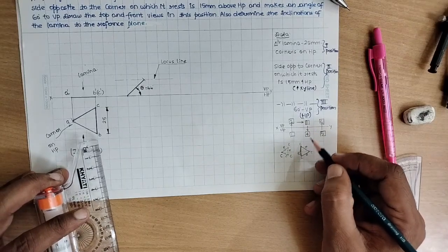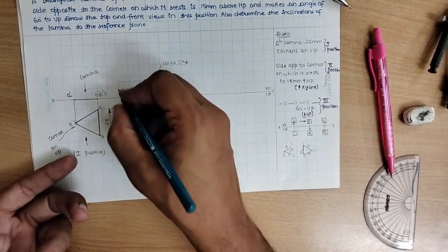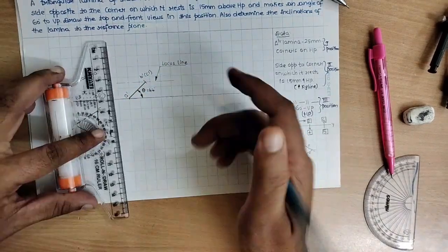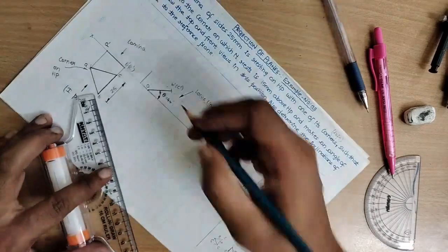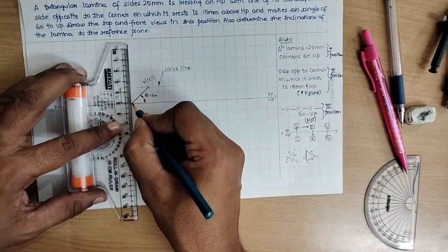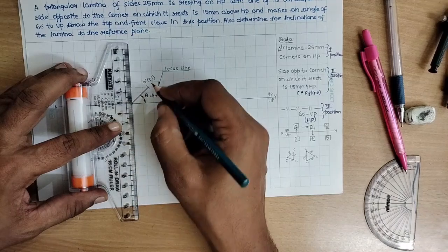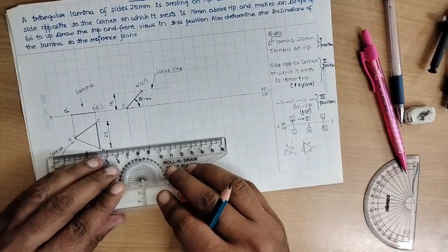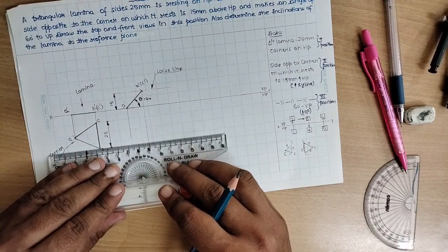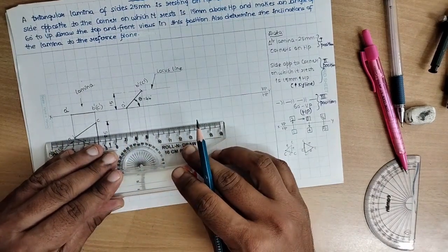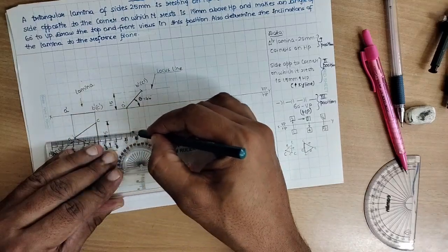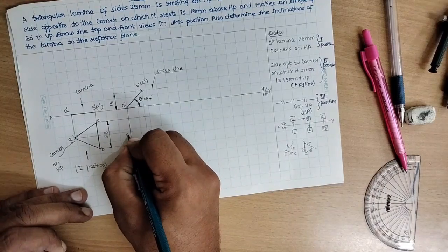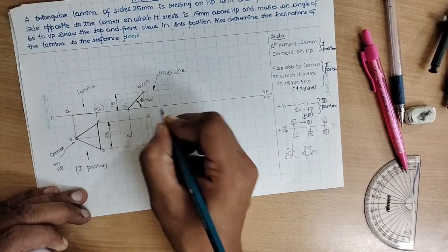We should come down to the fourth drawing. Meanwhile, this is the point A dash, this is the point B dash within the bracket C dash, and this distance is 15 mm. Next, drop a perpendicular projection line from the points A, B and C. Similarly, draw a horizontal projection from the point B, from the point A as well, and from point C as well. This would be the point A, this is the point B and the point C.